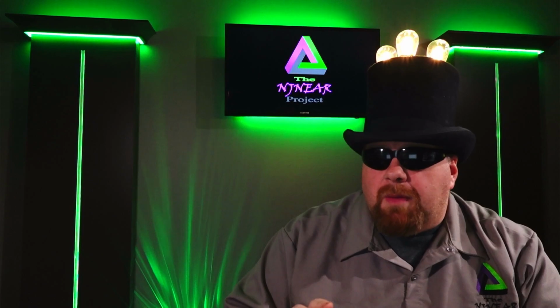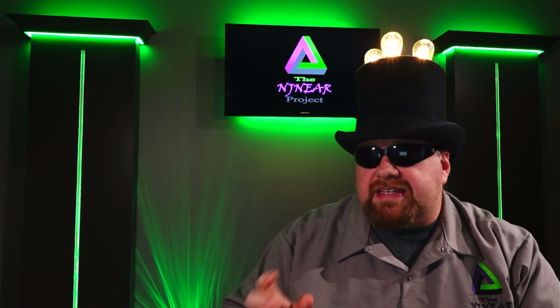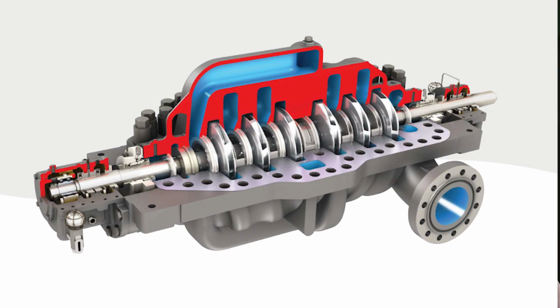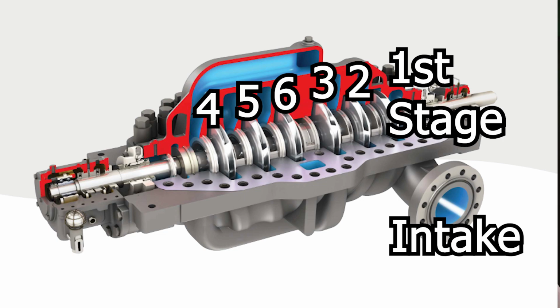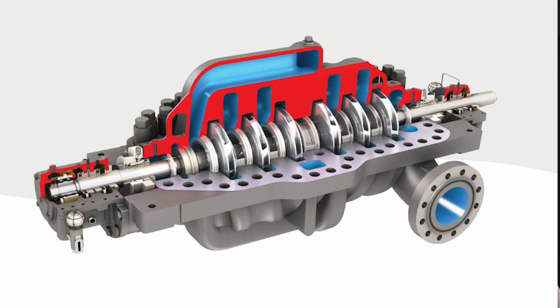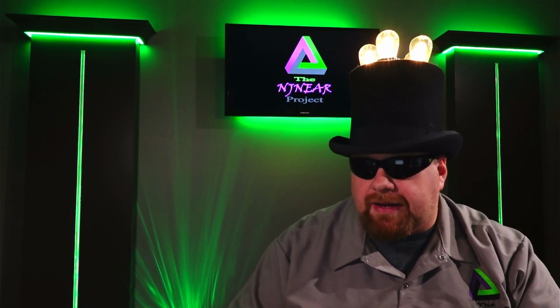I'm going to go a little bit more off base here and show you a multi-stage pump like I used to work on as a design engineer. This is a Flowserve axially split multi-stage called a DMX. Fluid enters here on the right and goes into the second and third impellers. Then the fluid crosses over to the fourth stage on the opposite side of the pump, with the impellers flipped in the opposite direction, and then the fluid flows through into stages 5 and 6 and discharges in the middle of the pump on the backside, which we can't see in this view. The main thing I want you to take away from this is simply having multiple impellers on the same shaft.